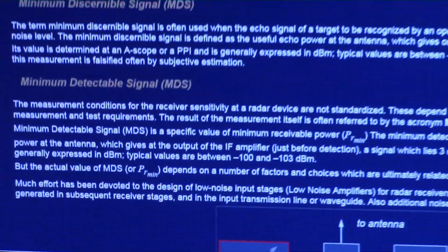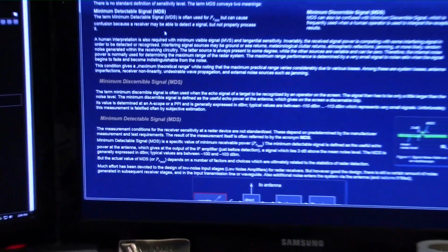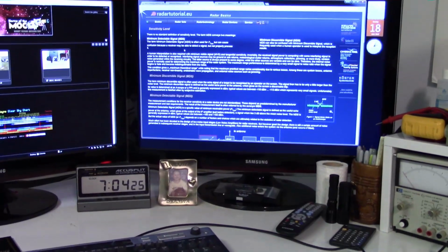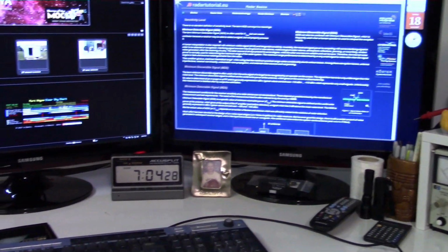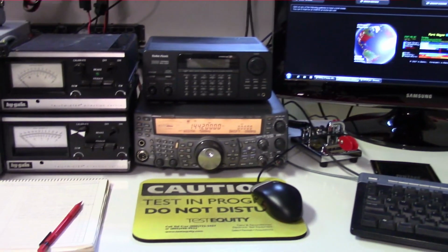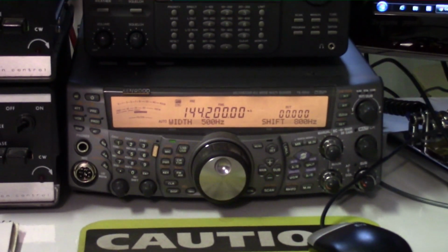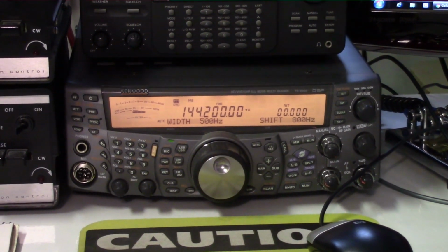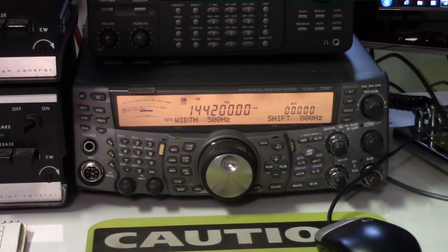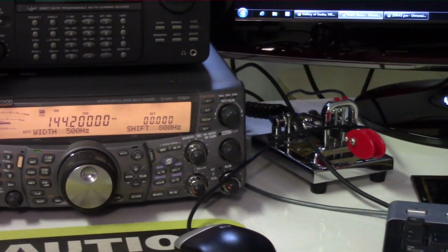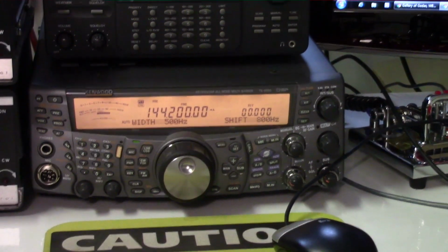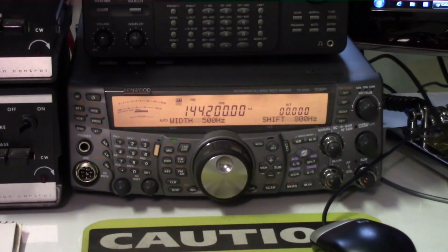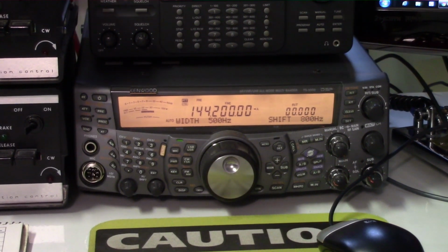Just as a side note, in my previous life as a Tempest engineer, we would have to characterize the detection system we used to perform our tests, and we used MDS. It was always referred to as minimum discernible signal. And the standards that we used very carefully explained the procedure that we had to use to measure that MDS.